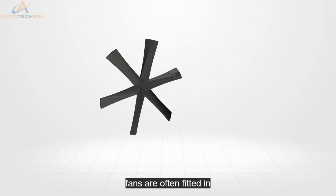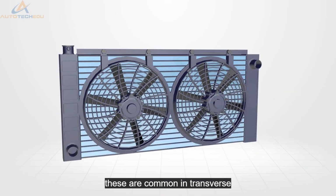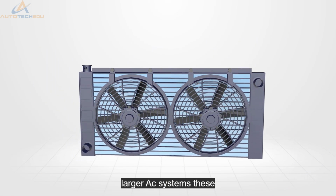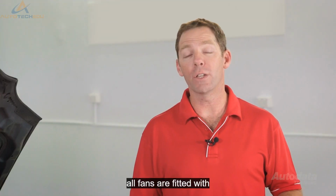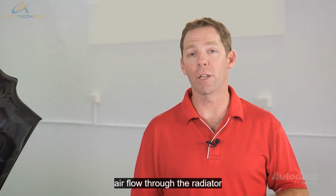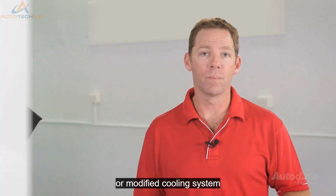Electric fans are often fitted in single or paired units. These are common in transverse engine configurations and vehicles with larger AC systems. These systems may be ECM controlled. All fans are fitted with a shield or cowl. These are there to direct airflow through the radiator. Cowls should never be discarded or modified.